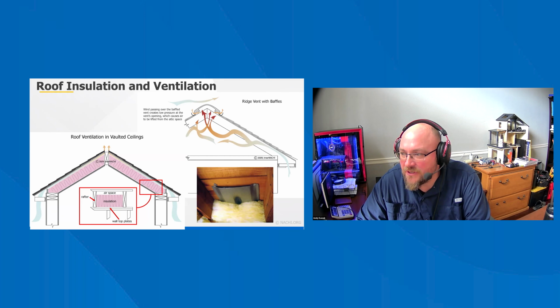There should be a minimum of 1 inch space provided between the insulation and the roof deck sheathing and at the location of the vent. This clearance can be provided by a rafter vent component, often referred to as a baffle. The ridge vent itself may have exterior or external baffles and a weather filter, like a mesh material, integrated into the vent's design to help prevent the entrance of rain or snow through the openings of the ridge vent component.